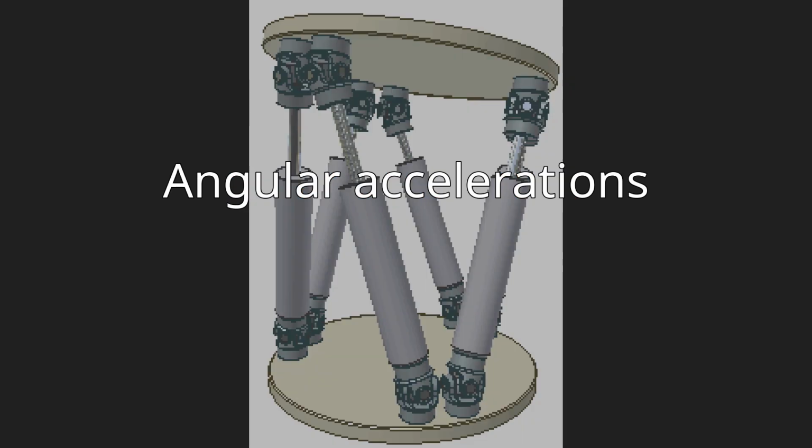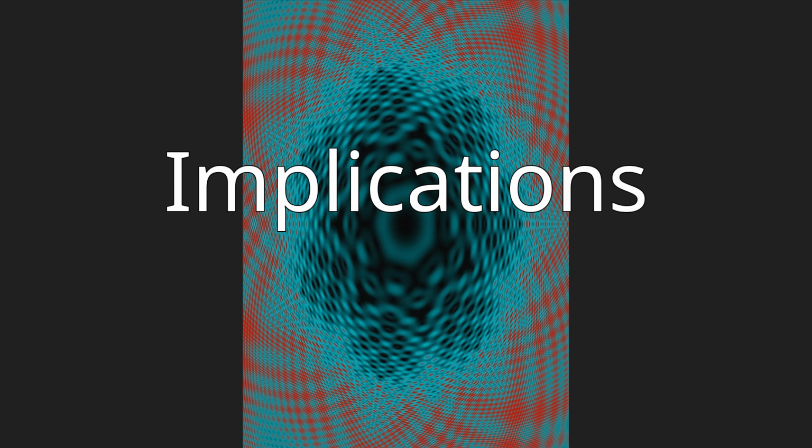Angular accelerations. Implications. The above studies indicate that the pilot's vestibular system detects accelerations before the aircraft instruments display them. This can be considered an inner control loop in which the pilot responds to accelerations that occur in full motion simulators and aircraft, but not in fixed simulators.